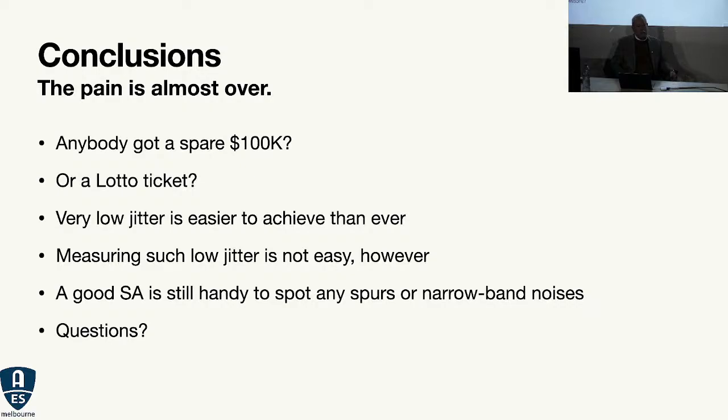I would say gear up to present day minus maybe a few years has typically been jitter in the 10 picosecond range, which is not a terrible thing because the kind of converters that you might have would be performance that would match that.